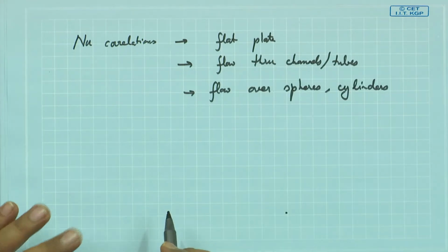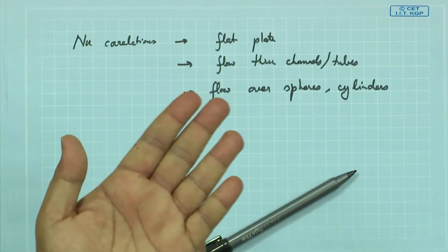Even flat plate for natural convection, whether it is facing up, facing down, because natural convection depends on gravity, right. So, the hot air has to flow up. Now, let us say if this is my hot surface, but I put it down, what happens? The hot air would like to rise, but it cannot because it is obstructed. So, it has to now go around and then find its way to move up in a plume and so on, right. So, the good news is all these correlations people have worked tirelessly and have provided this for us.